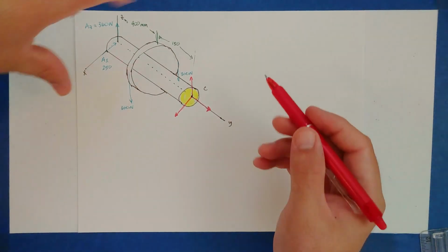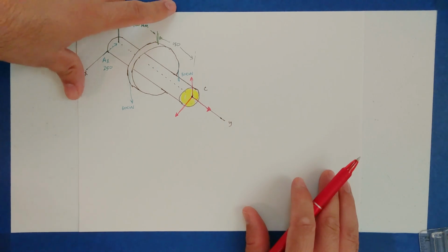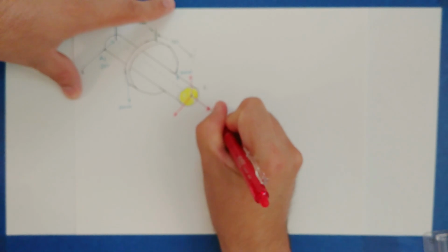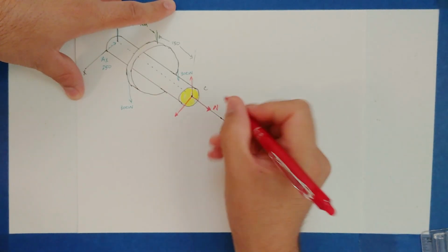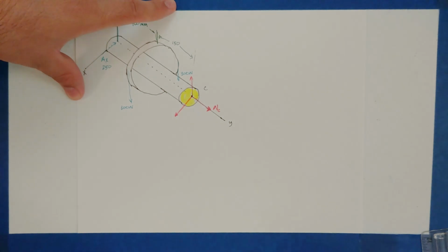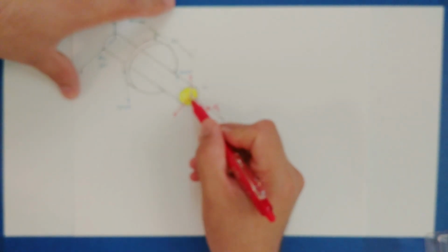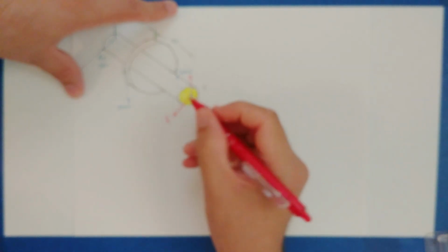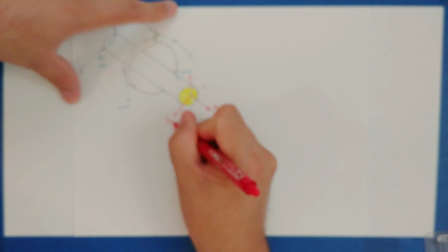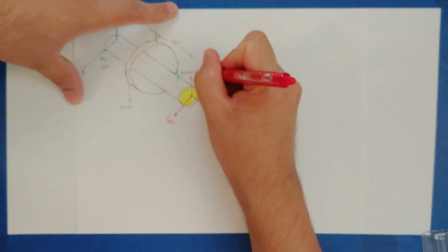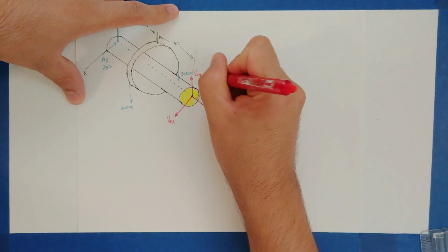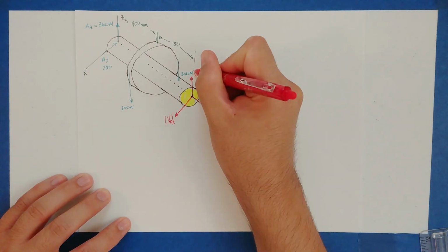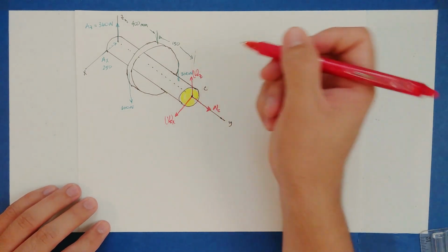Sorry. So from solids, we know that these forces have special names. This one on the Y, which points away from the section, is going to be the normal. So we'll call it N. You might see it as NC, like the normal at C. Next, we have this one, which is parallel to the cut. This is the shear force, about the x-axis VCX or VBX. This is VCZ. Sometimes you'll see it like this. So the shear force at C about the X, the shear force at C about the Z axis, the normal at C.